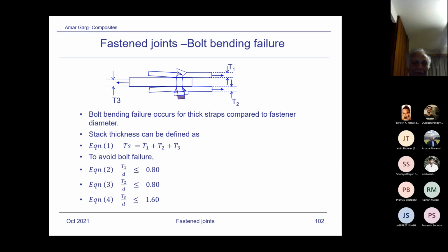What happens here? There would always be an attraction. When you have some bearing allowable data, suppose we are dealing with about 600 megapascals of bearing stress allowable for the joint, and you choose a fastener like a 6.4 millimeter or quarter-inch diameter fastener. Your load is some amount, and there's an attraction to use this. I'm trying to design the joint, and doesn't matter if I've chosen a quarter-inch, 6.4 millimeter fastener, this is my allowable, so I can keep on increasing thickness until I achieve a positive margin.